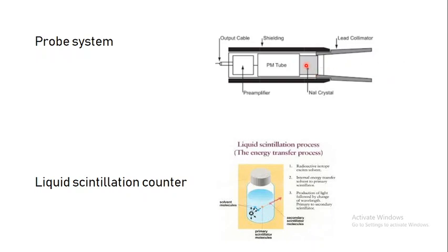The photons emitted by the crystal are received by the photomultiplier tube. These photomultiplier tubes exponentially increase the number of electrons, making a great impulse of current, and this pulse of current is pre-amplified, then amplified, and then analyzed into reasonable counts.